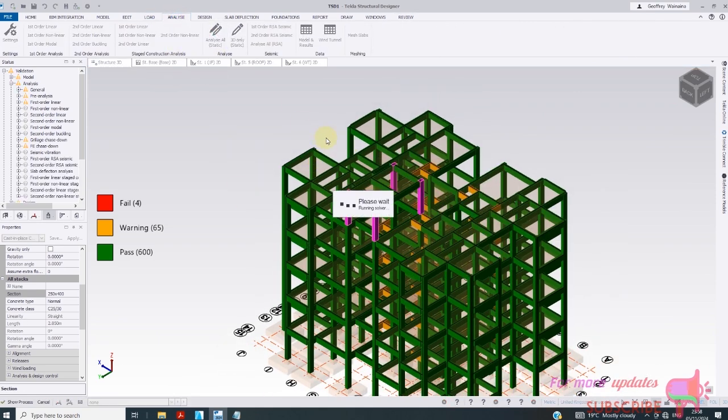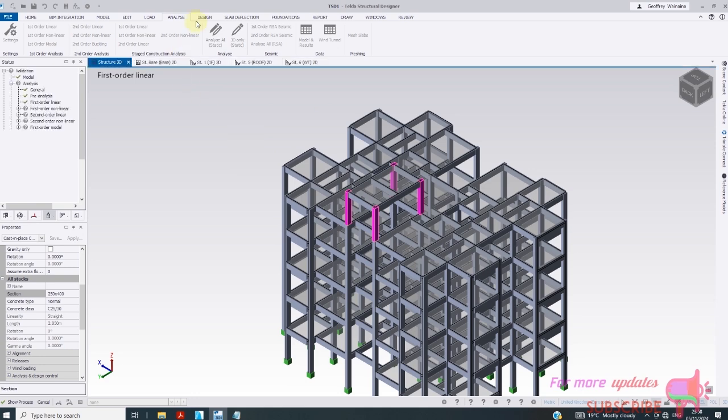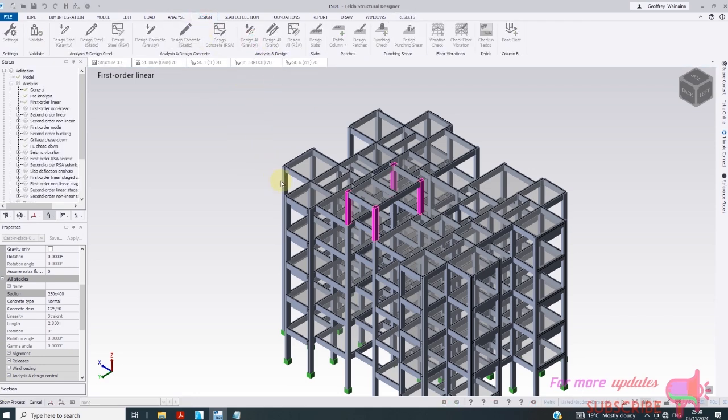Because I have masonry walls, my walls are braced, so I will just analyze for gravity, and also because the location is not prone to earthquake. But that is not justification. I think you should go for static design, which is the most critical, that is, you include lateral loads such as wind, earthquake, etc.